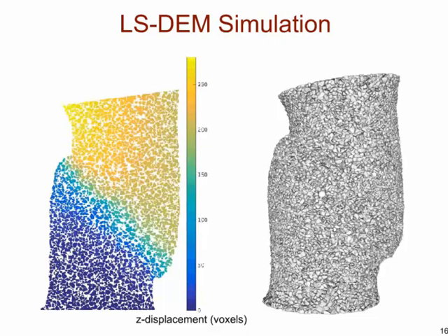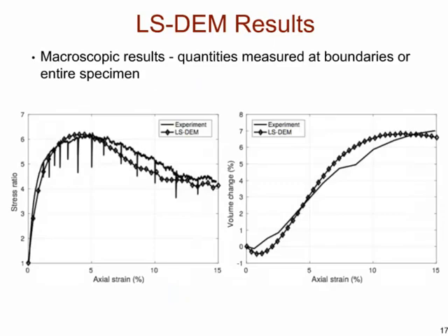And you will notice from these images that the platen is allowed to rotate, and that was captured also in the model. The platen is only prescribed the vertical displacement, but the rotation is free, so that the platen can rotate at will. And we're prescribing here the confinement that was 50 kPa, which is the same as in the experiment. So I think these are the most interesting results. And next one's here.